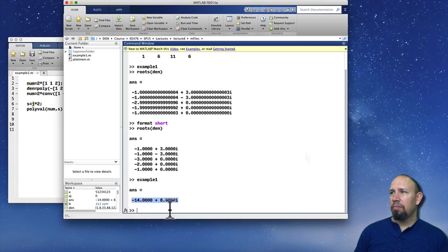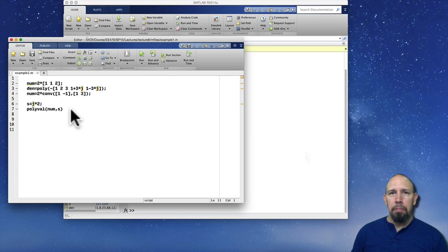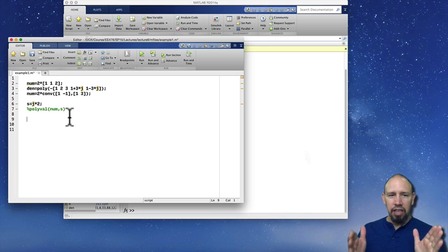Okay, so that's typical for evaluating a polynomial, even if it has real coefficients, with a complex quantity. Okay, so I'm going to comment that out. So polyval is helpful in evaluating a polynomial at some value of s, of course. Or it could be a polynomial in z, and you evaluate it at z. So the polynomial basically is a row vector. It's understood that it is a polynomial, even though it is actually a mathematical description.